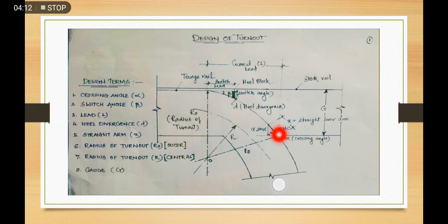That part is called the straight lever arm and denoted by x. As well as here the inclination subtended is alpha, because these are alternate opposite angles, and the vertical ordinate formed here is x sine alpha. So that is regarding the straight arm.